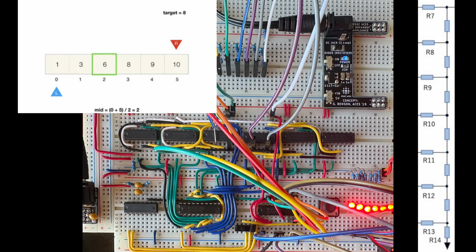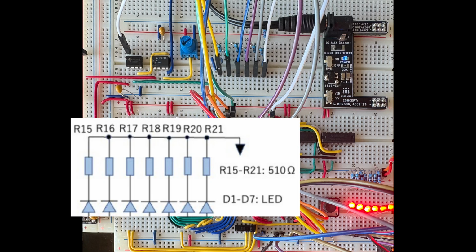When the approximation is complete, the final digital value is latched and displayed on the LED outputs. Each LED represents 1 bit of the binary value, allowing the user to visually observe how the circuit translates the analog input voltage into digital representation.